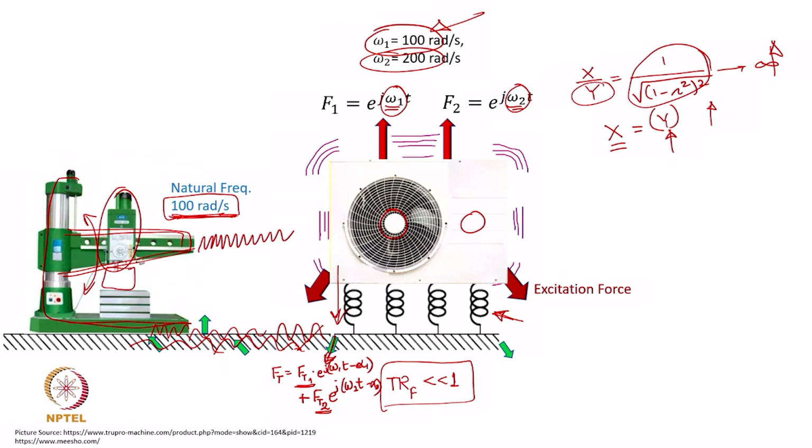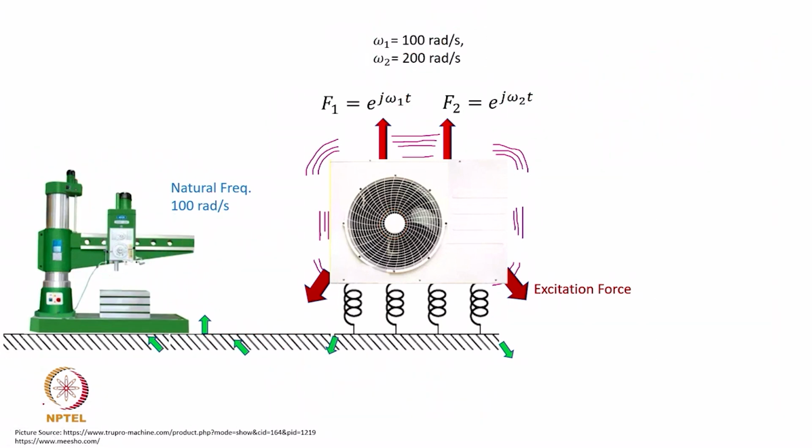Now, what is going to happen? You are going to operate this machine for some finishing operation on your delicate structure being manufactured, and if your tool itself starts vibrating, then that vibration is going to create products of bad quality. And this has happened in one of the factories nearby. There were a large number of rejections of the components being manufactured only because there was some heavy forging hammer operating nearby, and the isolation was very poor, and that can create trouble. So, the point here is you still need to take care of the base excitation as well.